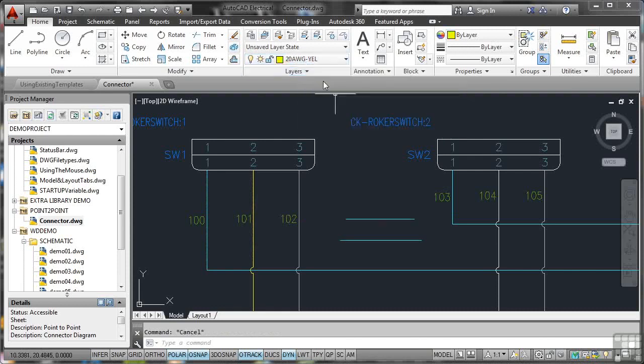So if you've got a whole load of layers that are on the 0 layer, the default layer, but you want to update them to a particular layer, use Match Properties. Find one of the existing colors that you need, use that as your source object, and then the destination objects are the ones on the 0 layer that you want to convert to the new layer. So there's lots of tools in there with layers that you can use, and as we work through this course, if there's anything about layers you need to know, I will make sure that I tell you.